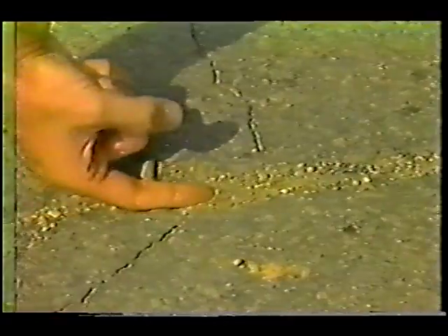Pavement with cracks wider than the thickness of your finger require more extensive repair than we are covering in this videotape. These wide cracks indicate serious damage of the road base that you should schedule to be repaired. For repair information, refer to the IRF videotape, Base and Sub-Base Repair.